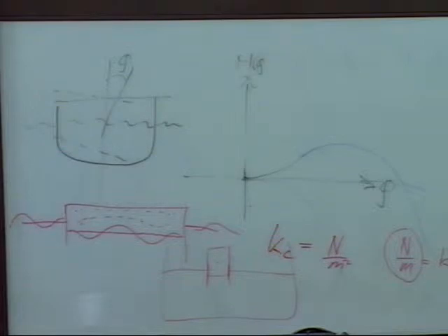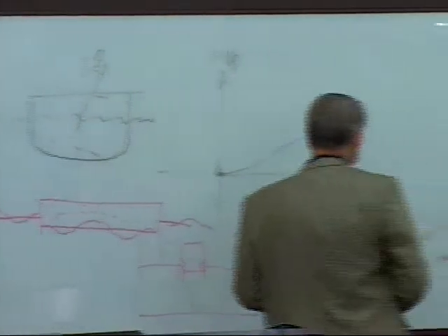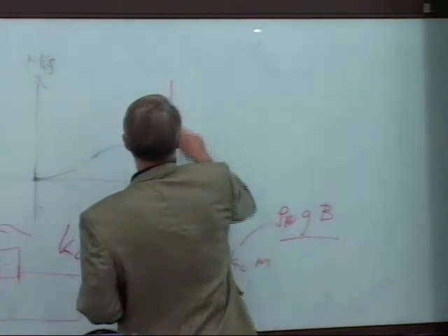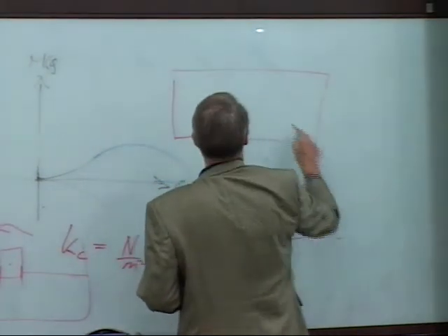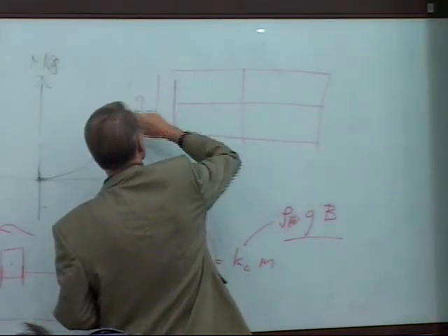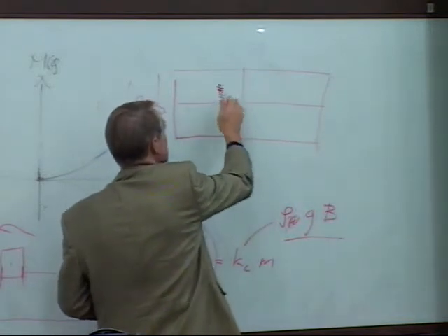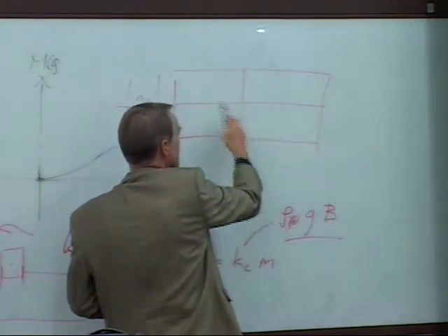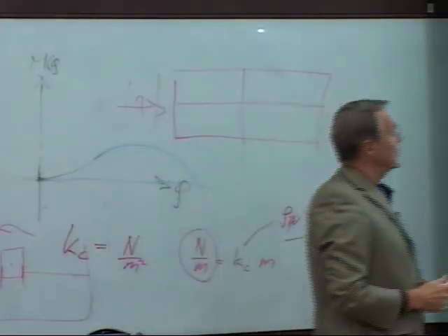The good news that we started with was that you get very small pressure differences in the structure, because the waves more or less just go through here. But then there's an example where you divide this space inside into 4 different chambers. So if you see this from above and we divide it like this, and the waves come in here, then this will be more stable because you have 4 air chambers instead of just 1.